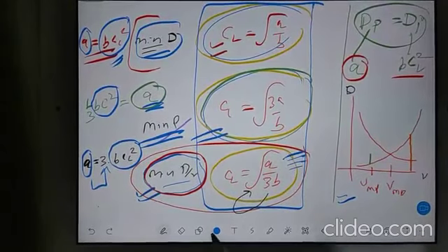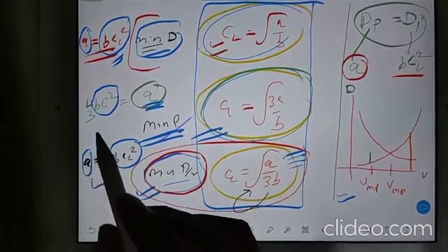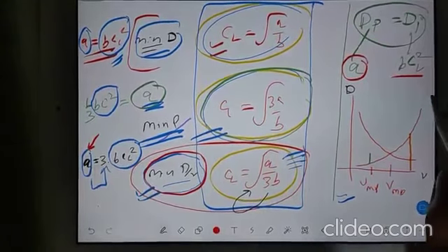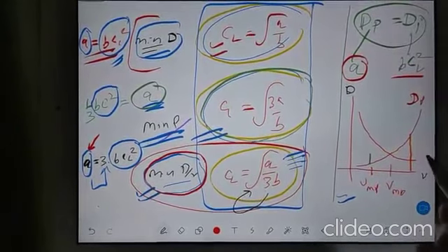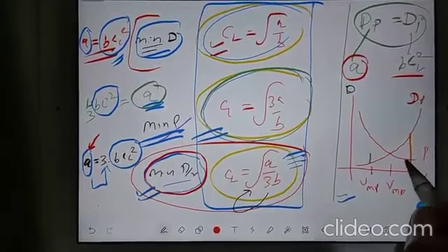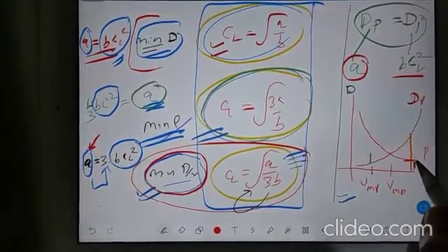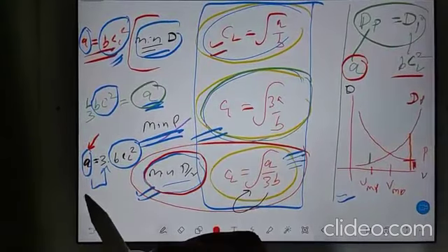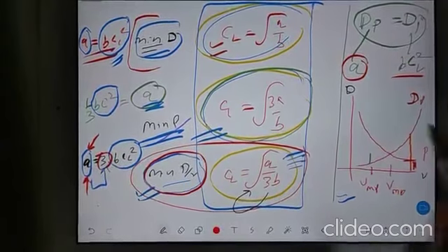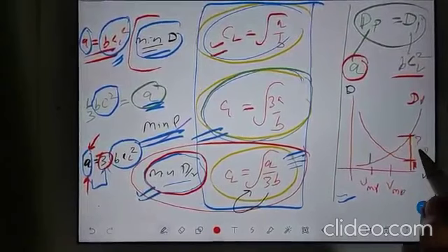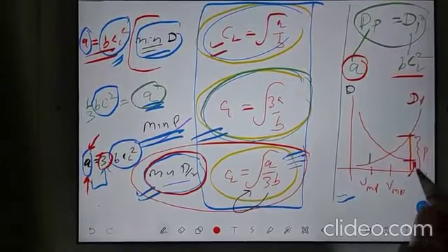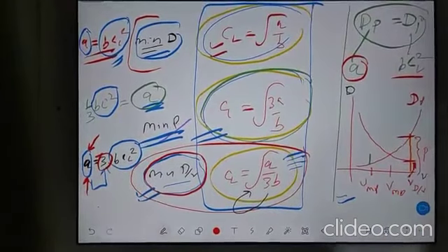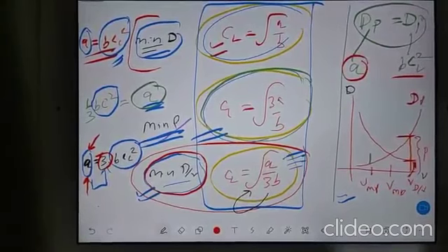So somewhere there, you can clearly see your A value. A is nothing but your parasite drag, and here you have induced drag. You can see the induced drag height is only this much, but your A height is 3 times. So consider this height is 3 times. So this is the velocity where you have the minimum D by V condition.